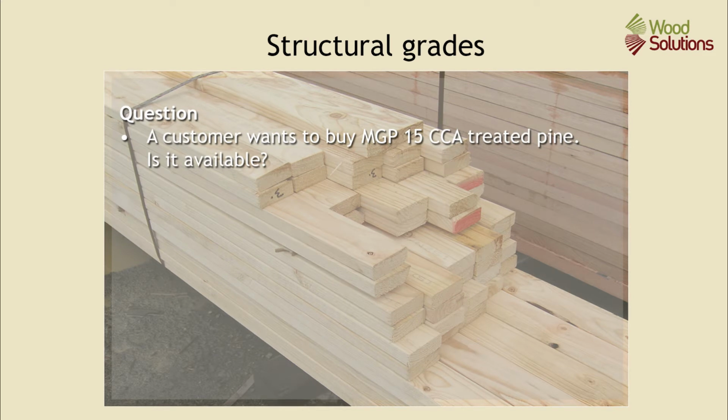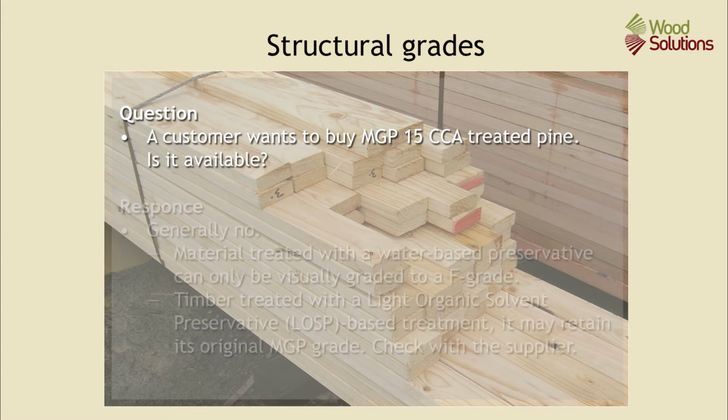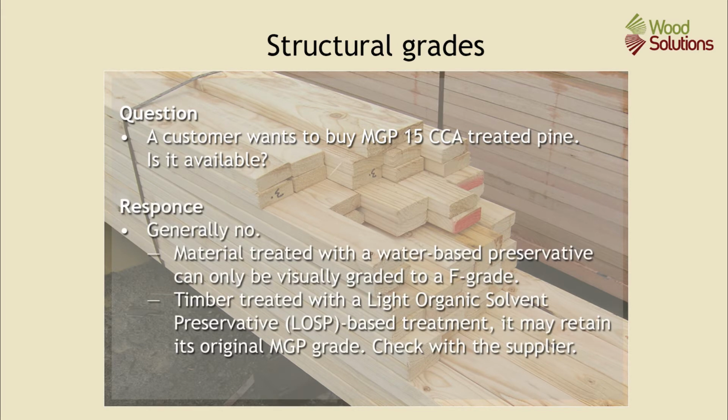A customer wants to buy MGP 15 CCA treated pine. Is it available? Generally, no. If the material has been treated with a waterborne preservative, it can only be visually graded to an F grade. An MGP grading doesn't apply to a timber with high moisture content. If the timber is treated with a light organic solvent preservative or LOSP treatment, it may retain its original MGP grade. Check this with the supplier.